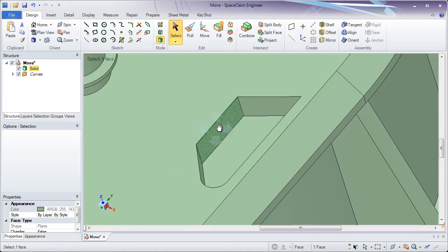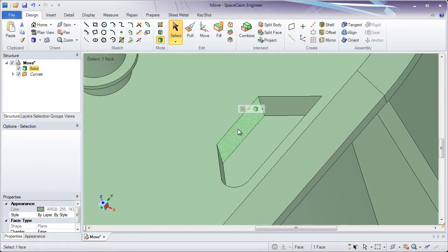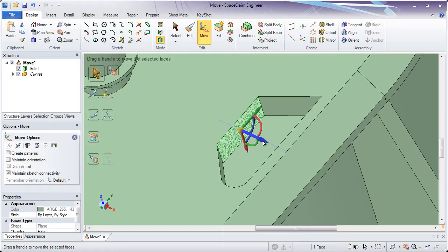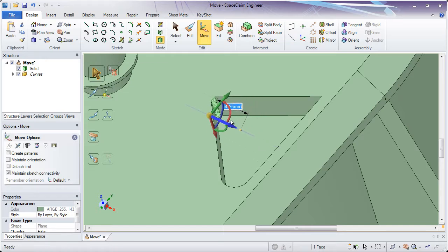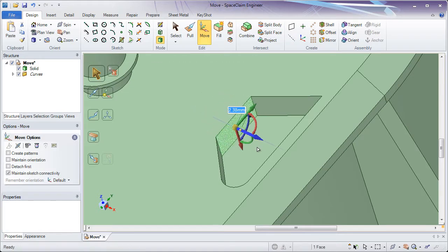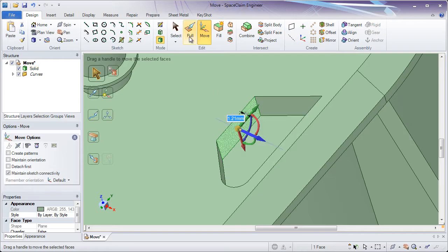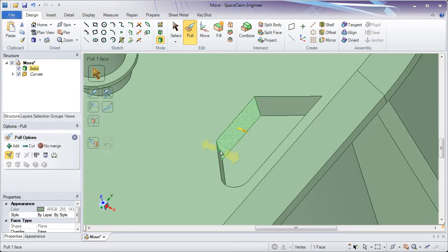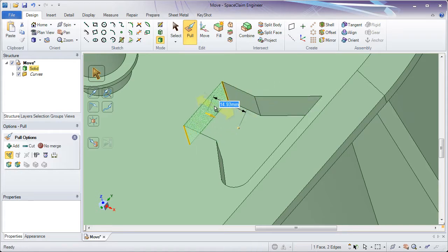Next, we'll look at one unique thing about moving. Remember, if I move one face, the faces next to it come together, just like pull. However, with pull, if we select on the edge on the left and the right, remember, it pulls them straight back or straight in and ignores that influence.